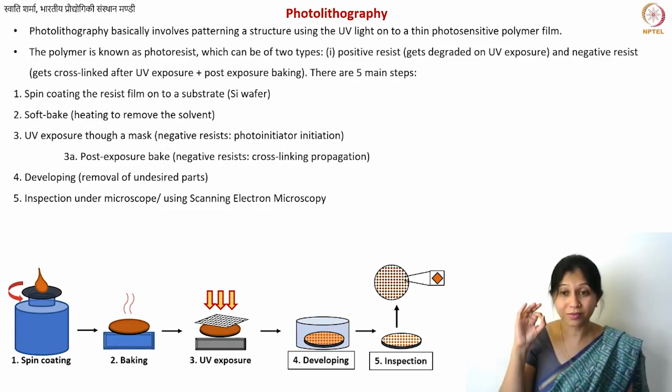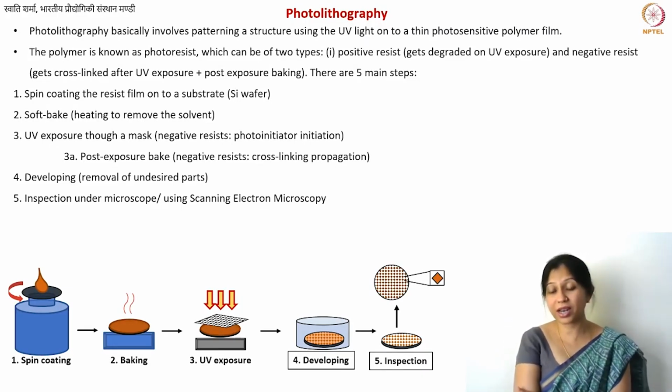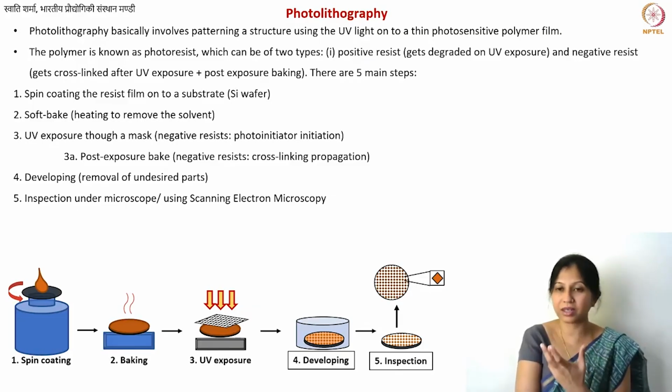you have an inert environment, and then heat it up to what temperature now? Well, 900 can already give you a reasonable carbon if the structure size is small enough. If it's in the micro domain, typically 900 gives you reasonable glassy carbon. Now there have also been questions about whether or not this material should be called glassy carbon, because traditionally what is called glassy carbon is prepared at 3000 degrees, and many people still believe that it's not just about the removal of the impurities, it's also about the kinetics of carbonization and graphitization, which may not be possible at temperatures as low as 900.